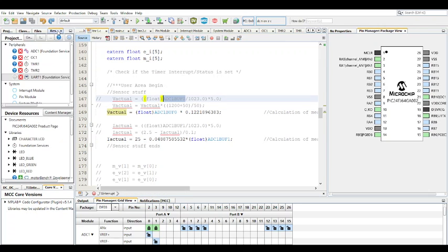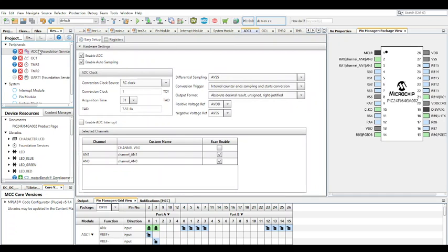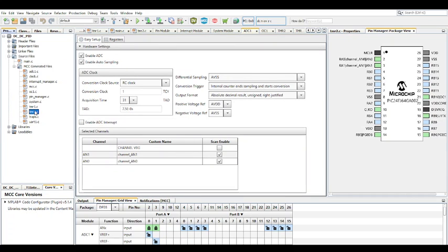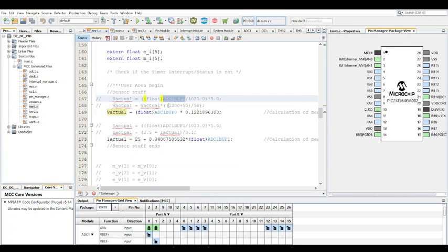Also with the ADC, in this particular example, let me not get too deep into that. For this particular PIC example, this ADC1 buff 0, the ADC is operating in scanning mode. What that means is it constantly scans the channels, records whatever value it gets and plugs them into ADC1 buff 0 and ADC1 buff 1, right?